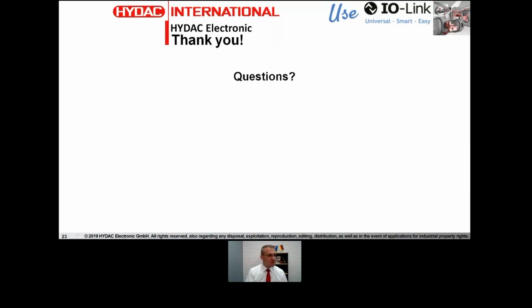Oh, there's another question. Can the IO-Link master be integrated into a HART system? No. IO-Link and HART are two completely different interfaces. They cannot talk to each other so far. And another question.